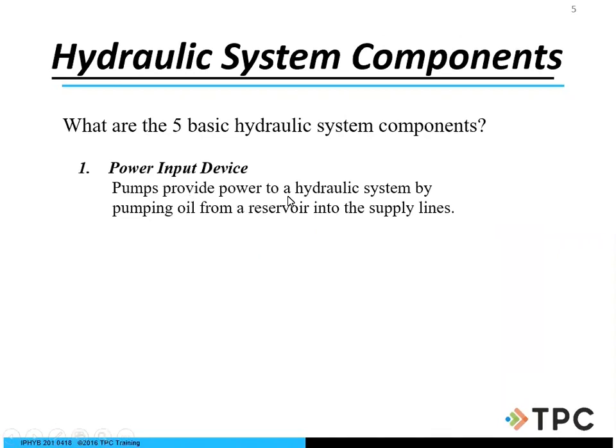A power input device, right? What is that? Pumps provide power to a hydraulic system by pumping oil from a reservoir into the supply lines. Well, we need to take a look at what size the pumps and motors are and so forth. What are we actually trying to pump? What is the viscosity of the fluid? How thick is it or how thin is it? All these factors come into play when we're working with our hydraulic system.